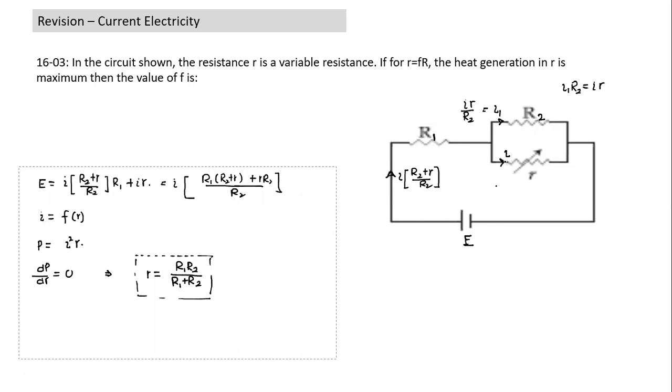In place of R, suppose I put a capacitor here, and I have to find the time constant for charging of this capacitor. To find the time constant, I use the concept of tau, equal to R equivalent C. What is the R we take here? What is the R equivalent in case of an RC circuit? How do you find the R equivalent? R equivalent is equal to the resistance between the terminals of the capacitor, by shorting the battery.